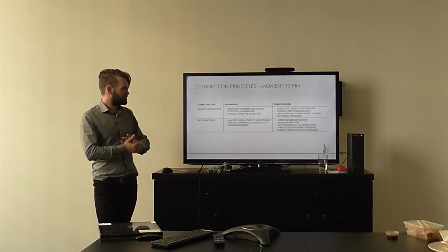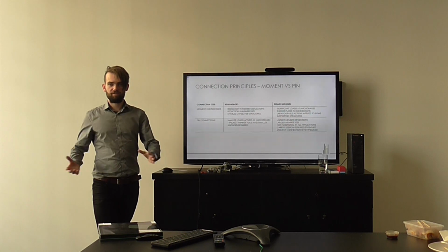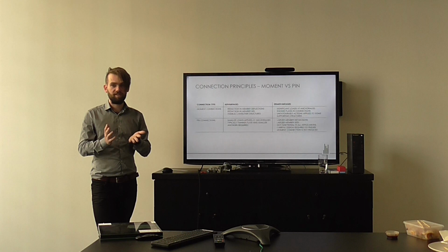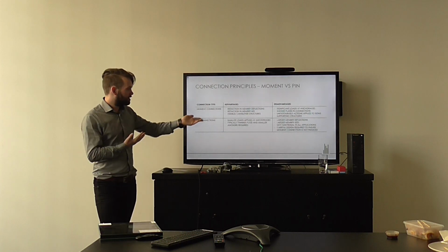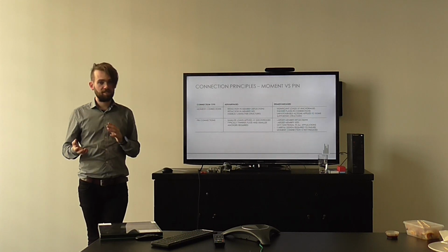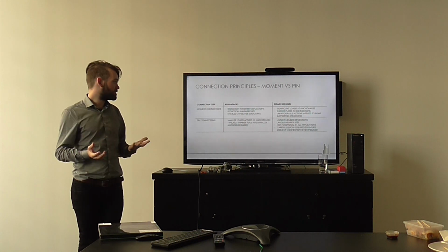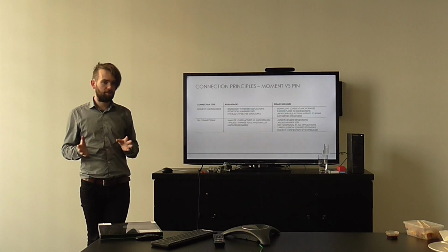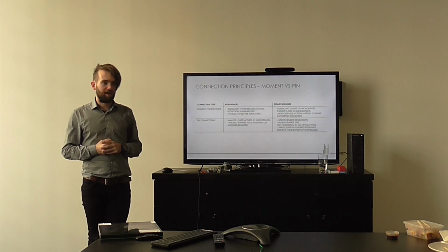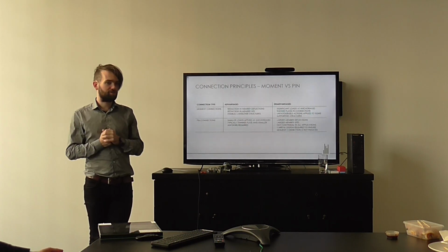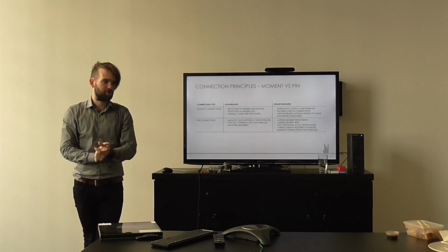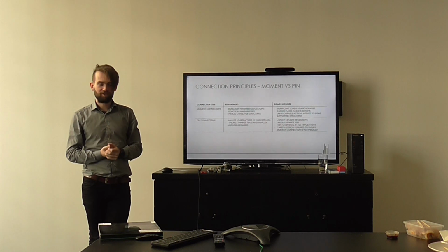As I touched on, there are a few advantages and disadvantages of the two. Moment connections, if they're intended, are fantastic. They reduce member deflections, they can typically reduce the size of members you need to use, and as I spoke about before with a cantilever structure, they enable them to occur. You can't make a balustrade stanchion with a pin connection, it'll just fall over. So you need cantilever connections sometimes.